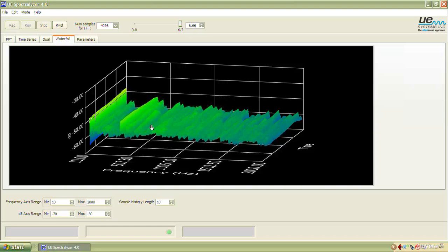Now, let's talk about this waterfall analysis. It is basically just giving us over time the exact peaks happening, and where they're happening over time. And you notice the peaks don't stay constant the whole time on those frequencies. The more it gets toward a red yellowish color, the higher the amplitude, the more severe or louder the sound is. The cooler colors, the less severe the sound is, or the lower the amplitude.